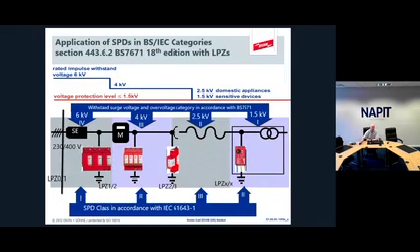So what we're looking at here is the relationship between the outside in. On the far left-hand side, I've marked up LPZ0. We go through the wall, and that's where the surge will come in. So the first SPD is going to be, say, a type 1 at the origin, where the service entry point is. The output of that is much lower.